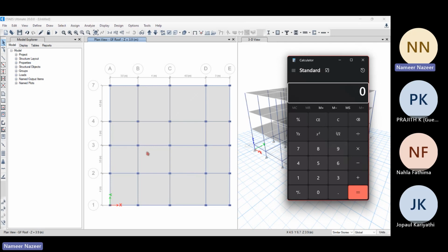So we can give a unit length, which will be uniformly acting throughout. I'm just giving a unit length 1, that means length into. Now I need to provide the breadth. What is the width of a wall? An ordinary wall width is 23 centimeter, right? I'm calculating in meters, so I'm giving it as 0.23. So this is the width of the wall into.